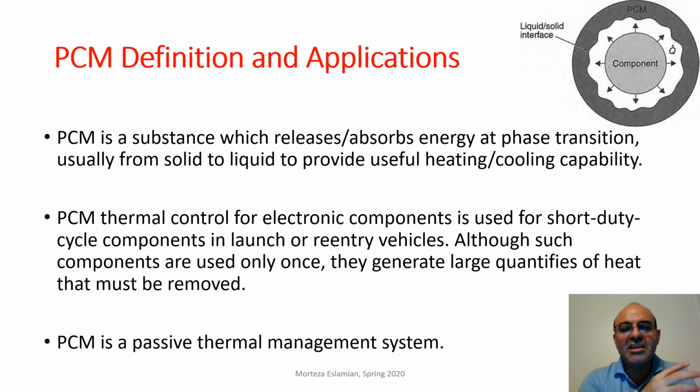But a lot of heat can be transferred, h_fg, the enthalpy from the liquid to the gas, that's the latent heat. So that's the concept. PCM thermal control for electronic components is used for short duty cycle components in launch or re-entry vehicles, short duty cycle components.